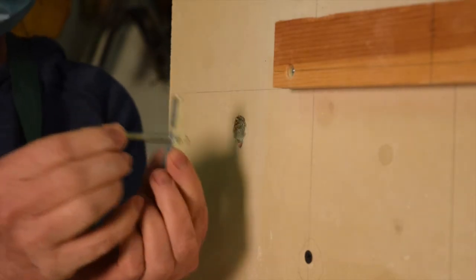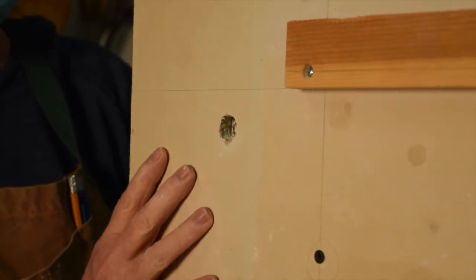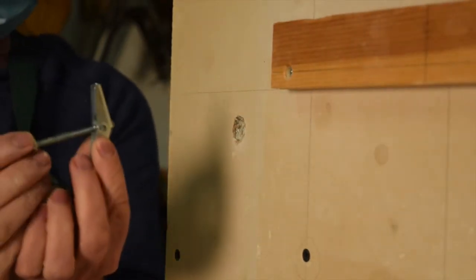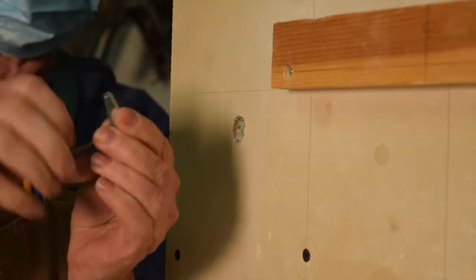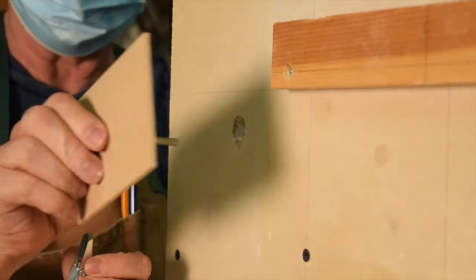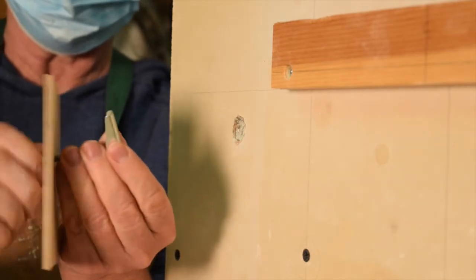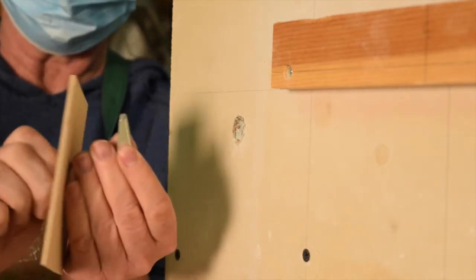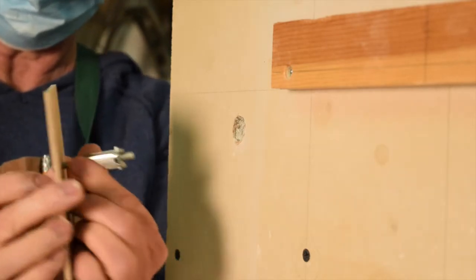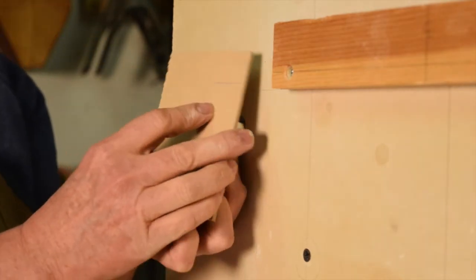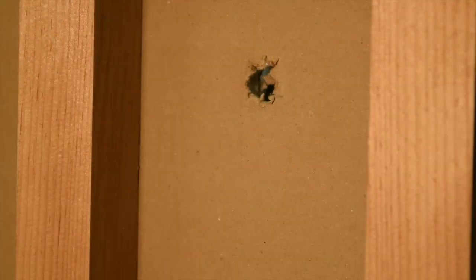With the toggle bolt, we have to drill a bigger hole because the toggle on the end is a little bit larger than an anchor, and it needs to fit all the way through. So I'm going to start by taking the bolt apart from the toggle clip, sliding the bolt through the piece that I want to attach to the wall, and then threading it through the clip at the end. Once I've done that, I can fold the toggle clip back and push it through the hole. So let's go to the other side and see what that looks like.